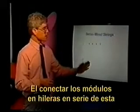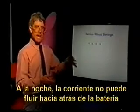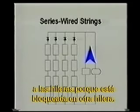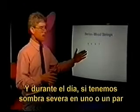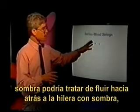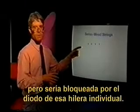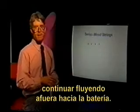Wiring our modules in series strings like this allows us to actually perform 2 functions. During nighttime, current cannot flow backwards from our battery into our strings because it's blocked at every string. And during the day, if we had some severe shading on one module or a couple of modules in one string, current from the unshaded modules might try to flow backwards down our shaded string, but it would be blocked by that individual string's diode. The current from the good strings would simply have to flow on out to the battery.